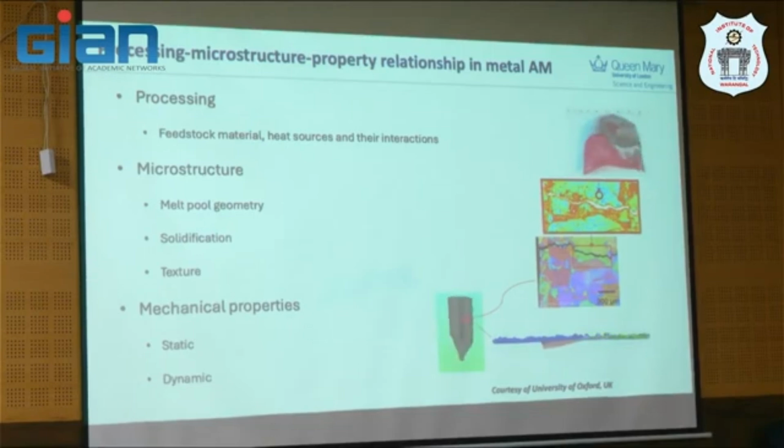And then you see here, this is Inconel 718, which is actually a non-printable material. So we map using atom probe, I think here at the University of Oxford, across the crack area after printing. It's in the as-printed condition. You will see that the stress field is actually not homogeneous inside the grain.